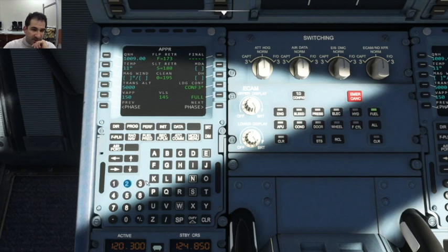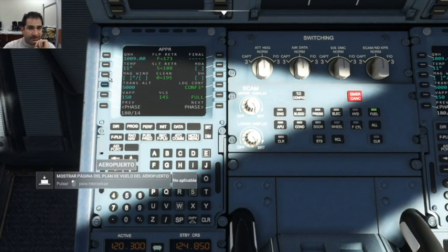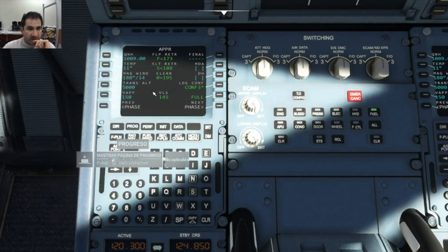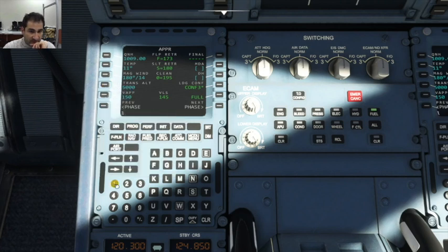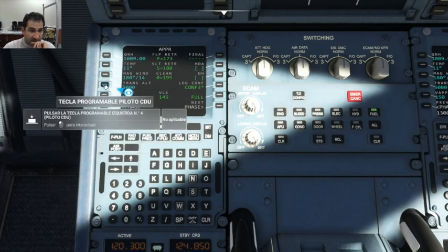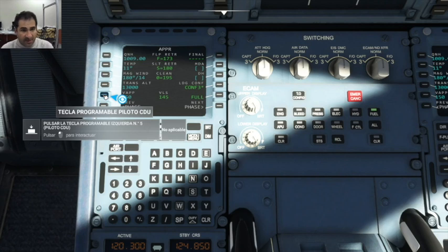Let's say it's coming up from the south, because we are departing 18, so it's a 180 slash, say we have 14 knots, right? So we can include here the transition altitude in Madrid Barajas. It's not 5,000, it's 13,000 feet, so we can include it here,